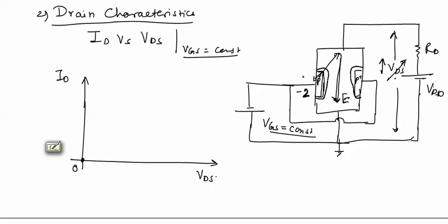But with increase in electric field, the charge carrier flow will also increase, and at lower voltages of VDS, it is seen that drain current ID increases linearly with applied VDS. Further increase in VDS will further increase the reverse biasing and hence depletion layer width.